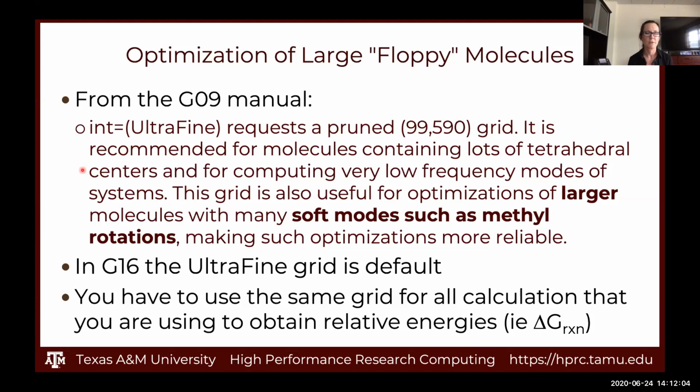If you need to move to a different piece of software, you had better calibrate and make sure that you're getting the same results as the previous software that was used. Or if you change major releases from, say, Gaussian 09 to Gaussian 16 in the middle of a project, you're probably going to run into problems. So you generally want to stay with the same major release because of the numerical component of density functional theory.